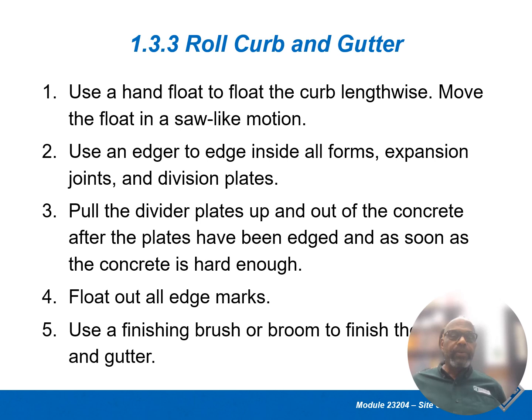Use a hand float to float the curb lengthwise. Move the float in a saw-like motion. Number 2, use an edger to edge inside all forms, expansion joints, and division plates. Pull the divider plates up and out of the concrete after the plates have been edged and as soon as the concrete is hard enough.